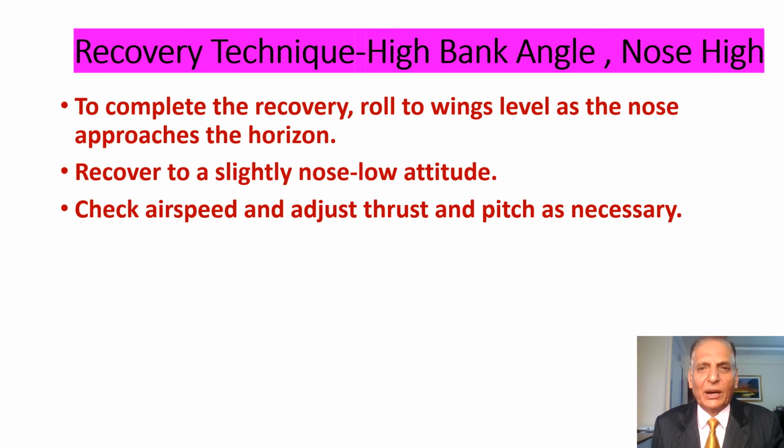To complete the recovery, roll to wings level as the nose approaches the horizon. Recover to a slightly nose low attitude. Check airspeed and adjust thrust and pitch as necessary.